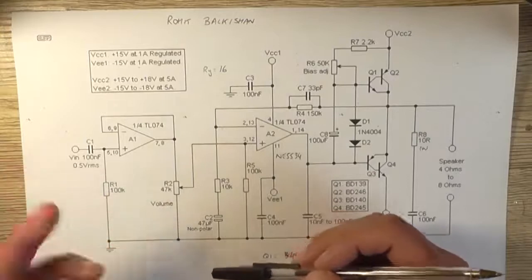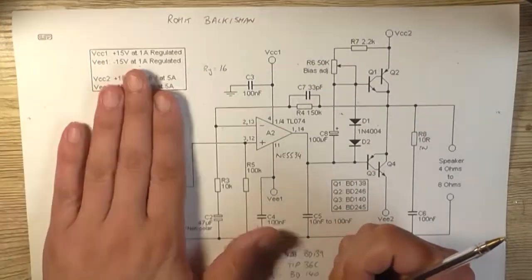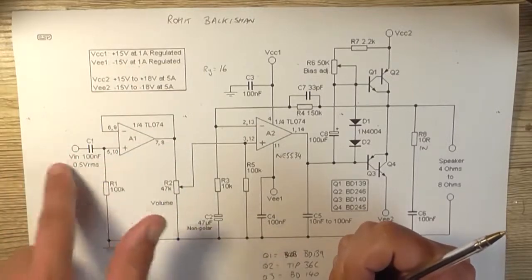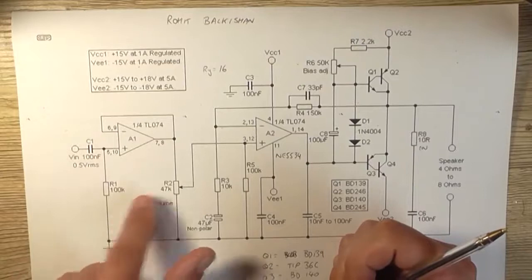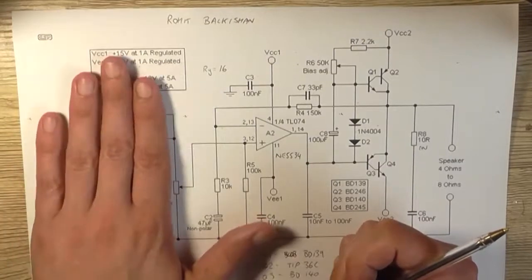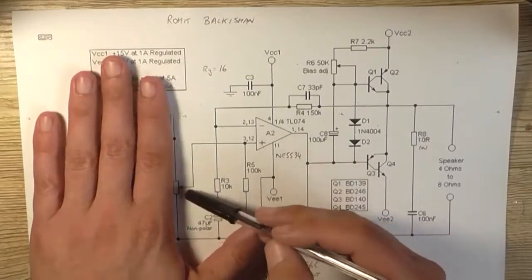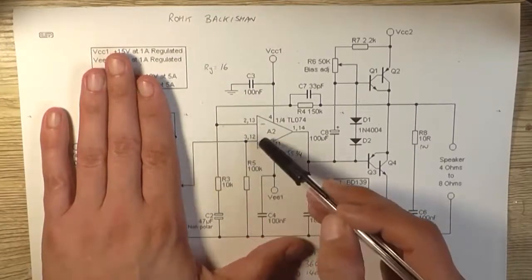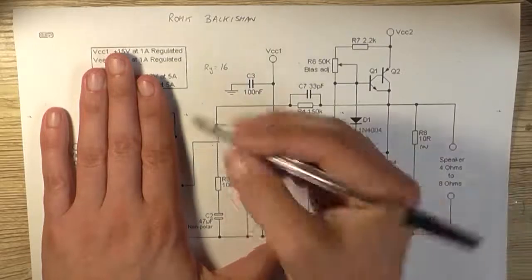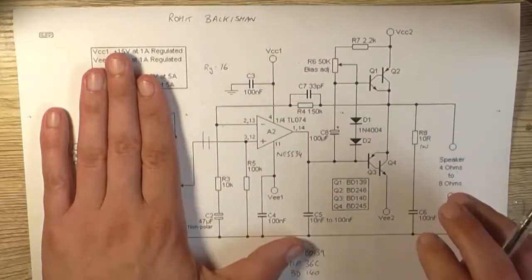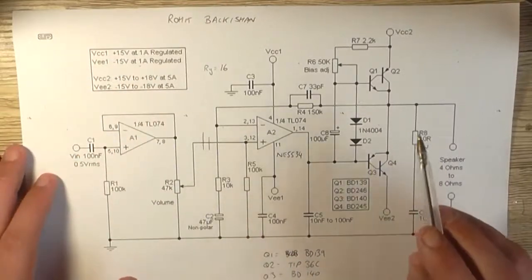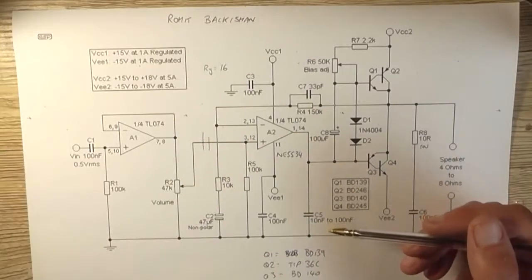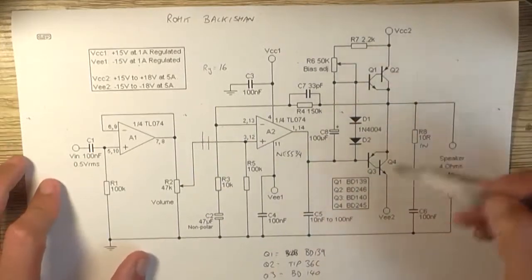I'm also going to knock off that part of the circuit because it's not needed. All this is a high impedance to low impedance source, so it's just a buffer. It's not really particularly needed. We're just going to go straight from this point, which is the volume control, which is now the input, straight into our first OpAmp, obviously via a DC blocking capacitor, and test it out and see how it performs. But as I said, we're going to look at the output stage first.